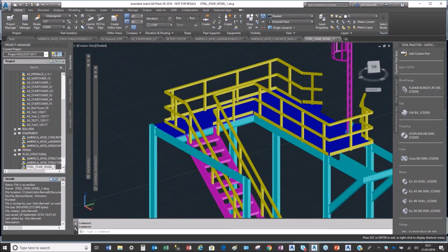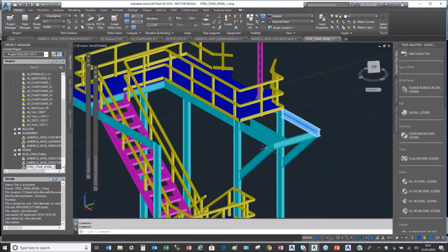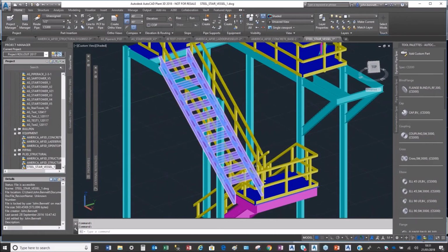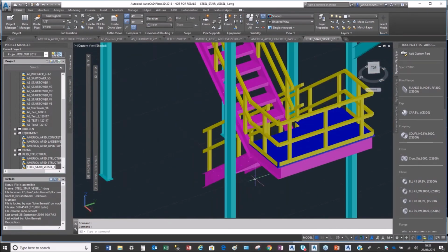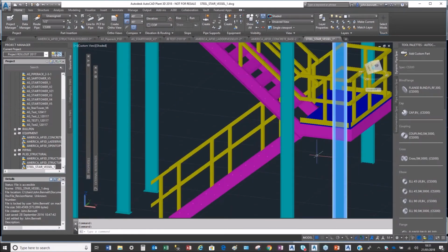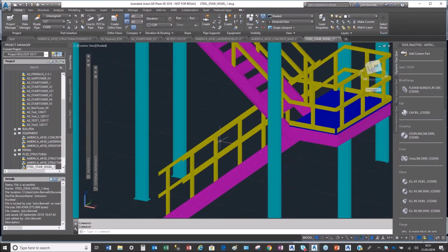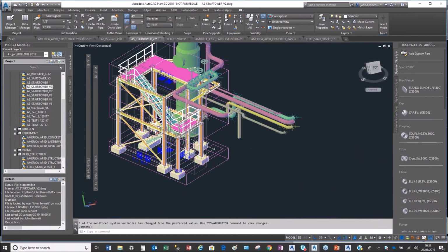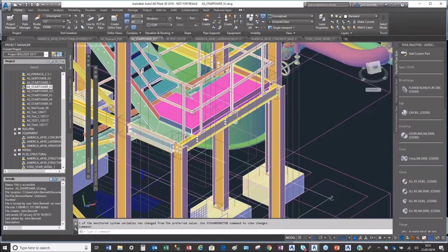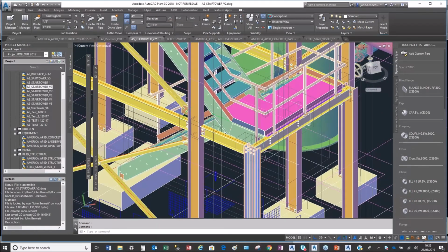Obviously, I've worked out the gallows bracket cantilever assembly here. Obviously, the hand railing didn't really configure with what I wanted. I even had to change the position of the stair. I had to provide some additional steel work to support the stair. So if you look at the model here, you can see I'm still back in Plant now, and I'm still seeing my Advanced Steel model back in here courtesy of the object enabler installed. So it enables me to see both together.